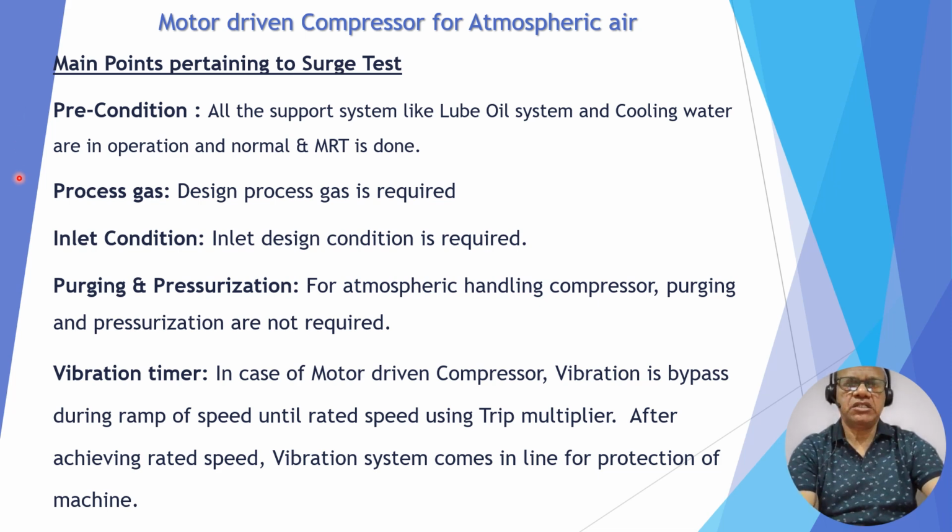Process gas, as per design, is required. That means since this compressor handles atmospheric air, atmospheric air should be available. Inlet condition should be the designed inlet condition. However, if there is some variation of inlet condition like RH or temperature, that is also okay for doing the surge test. Purging and pressurization for an atmospheric air handling compressor are not required because it is already filled with atmospheric air.